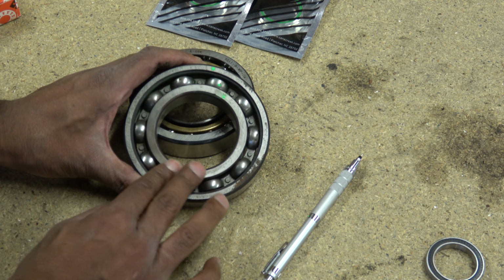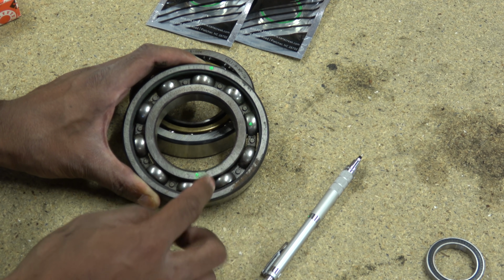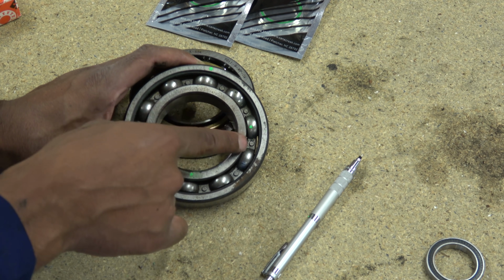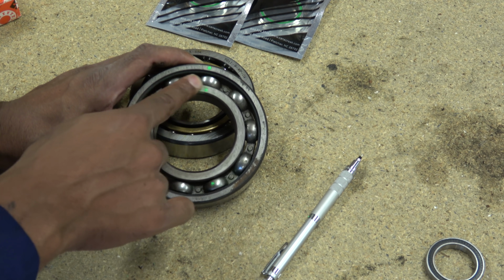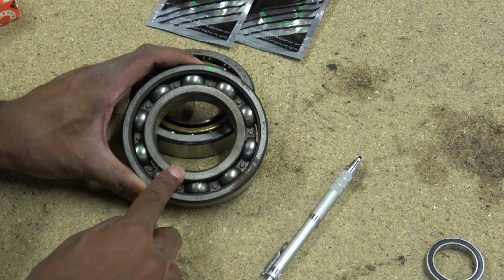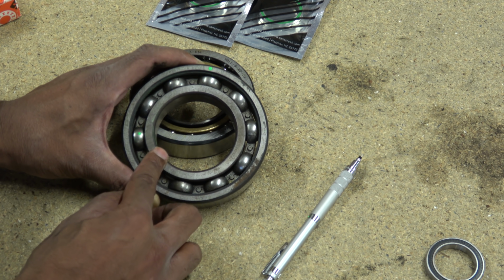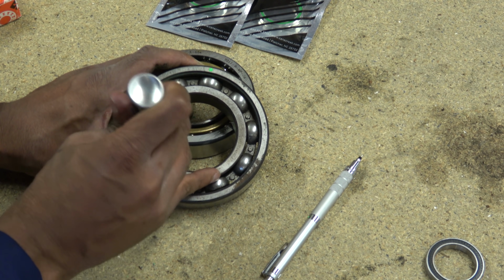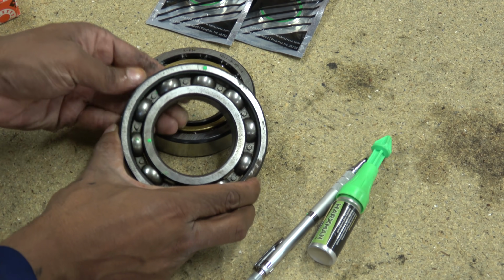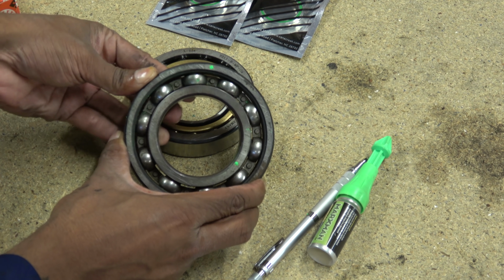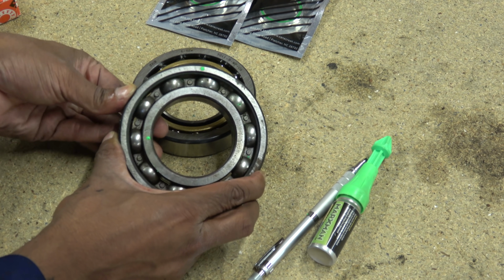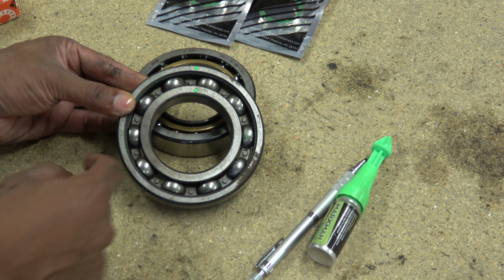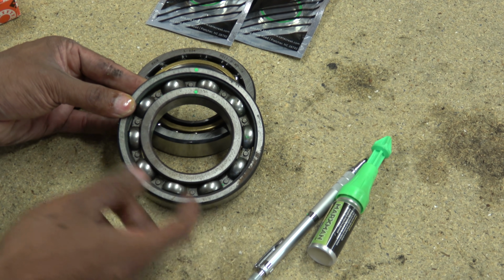If I start spinning the inner race around, you can see that the inner race is 180 degrees from where we started, but the cage has only moved sort of to the 2 o'clock position. So it's always playing catch up. At this point, there, where the mark's just rubbed off, that's where it caught up. I'm just going to mark it again. And this process carries on. So we've got the inner and the outer lined up again, and the cage is off to the side. They'll all come back to meet at a certain point, and they are called fault frequencies.